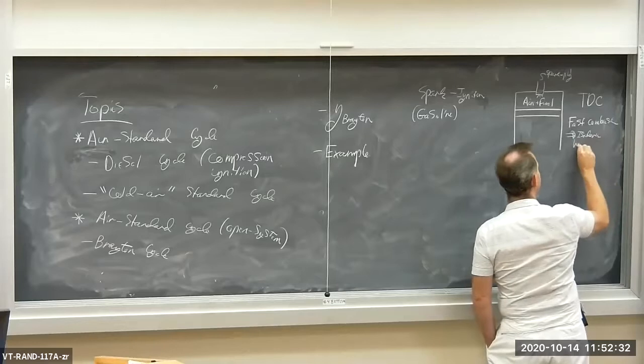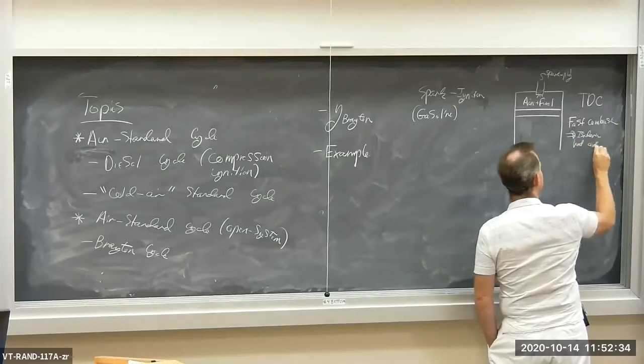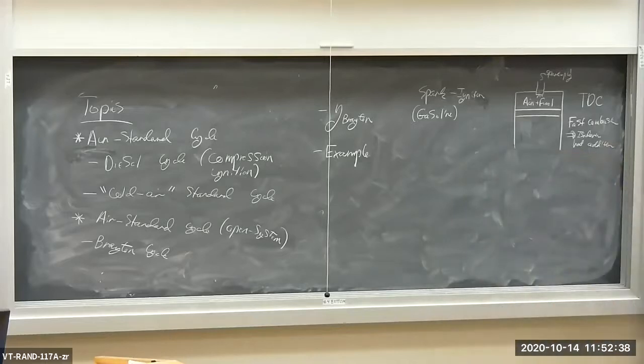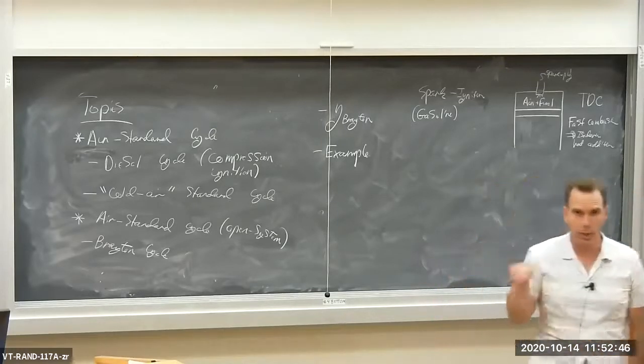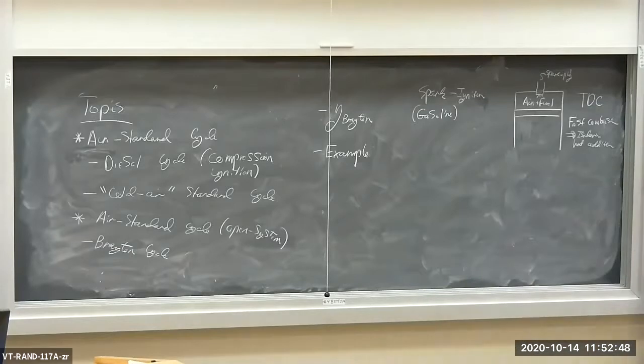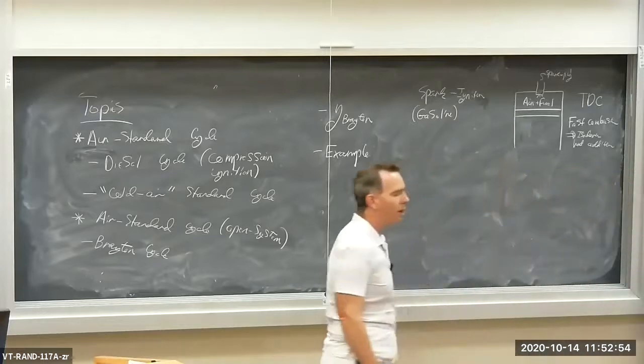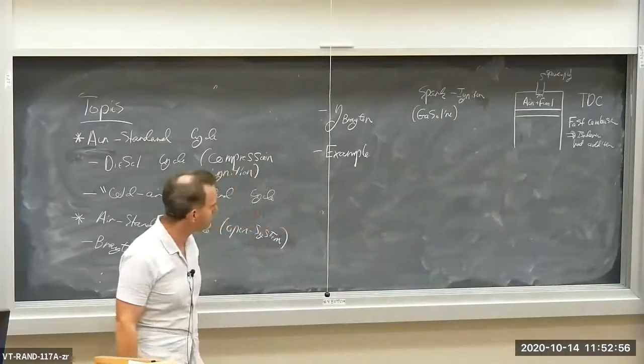Okay, so that's what happens with the spark ignition or gasoline engine. Very fast combustion process, faster than the rate at which the actual engine is turning in terms of RPM. The combustion process is much faster than the speed of the engine, so we assumed it was constant volume combustion.